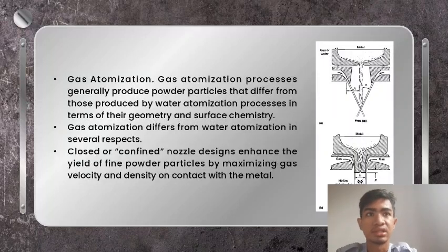Gas atomization. Gas atomization processes generally produce powder particles that differ from those produced by water atomization processes in terms of their geometric and surface chemistry. Gas atomized powders are typically most spherical in geometry and possess a lower surface oxygen content than their water atomized counterparts.